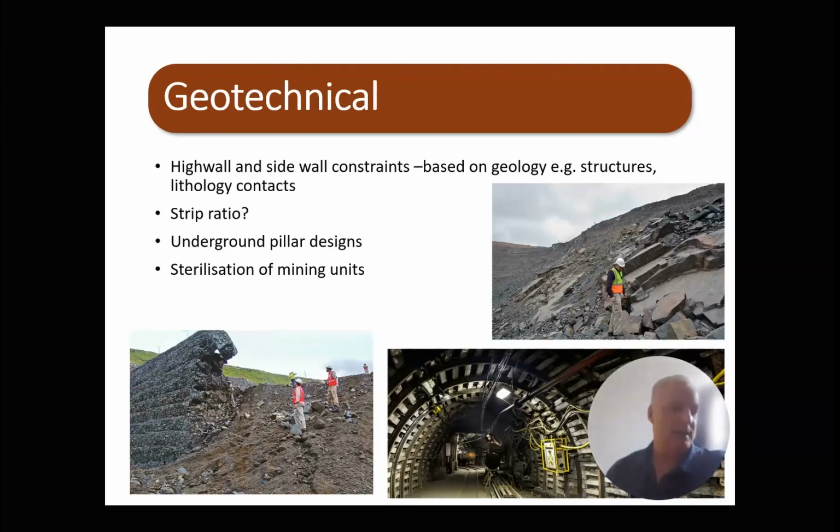If you have a very flat-lying deposit, your strip ratio tends to be higher. So you need to understand that depth would be associated with that. All of those sort of things, they'll feed into later. Now, as we go through, you might think that I'm considering everything almost from a feasibility aspect. No. I'm going through some of these things, just making sure that you understand that it's not something that is an issue that you can't reasonably say we can deal with. That's great. So things like underground pillar designs, you don't need to do pillar design, but making sure that when you've thought about it, you've considered it.